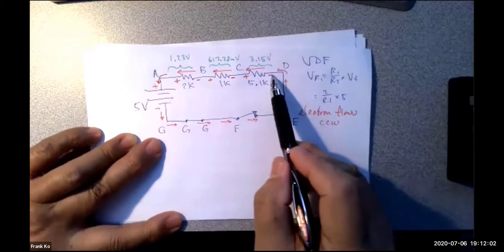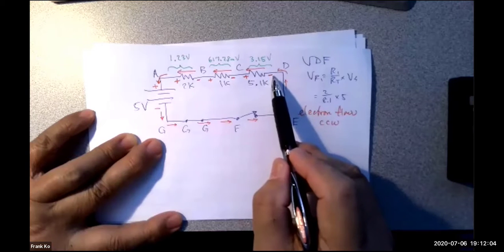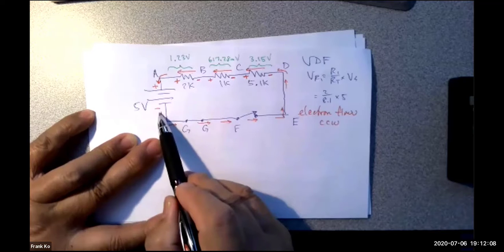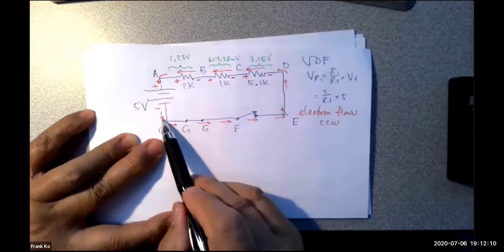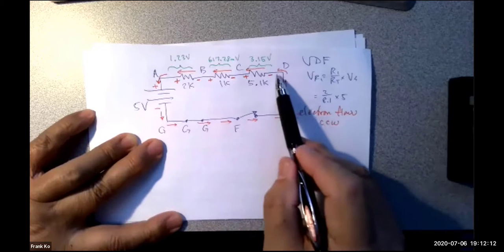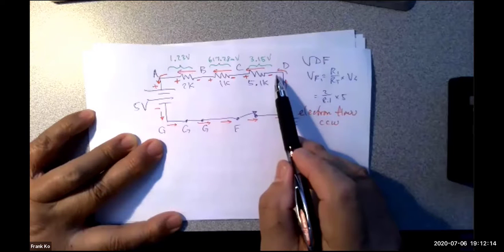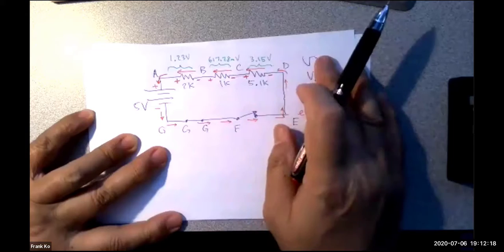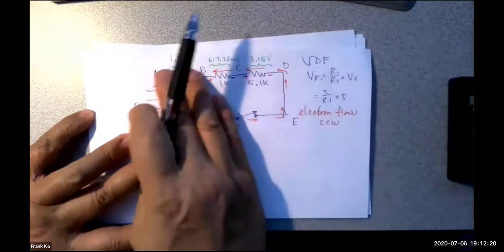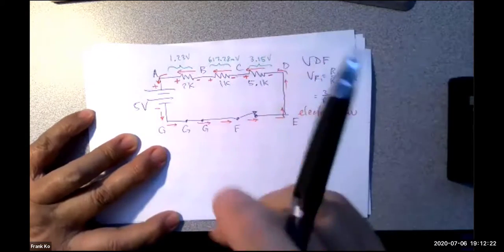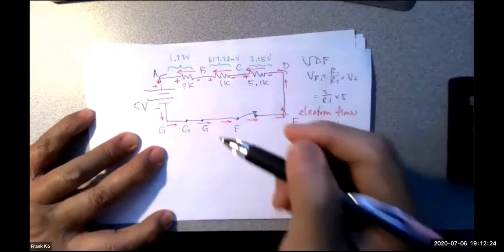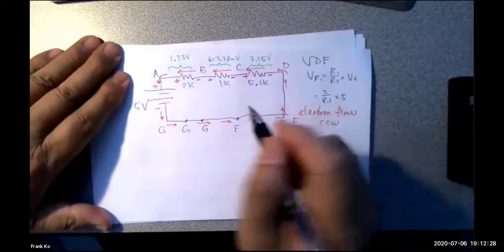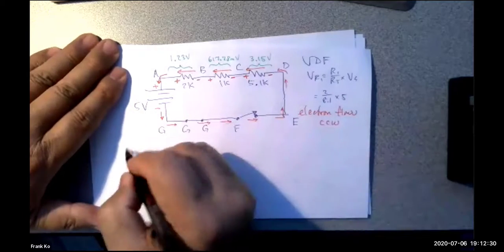This resistor over here, the last one, R3, has a wire that attaches all the way to the negative plate of the source. So as this plate is negative and there's a wire all the way to this side of the resistor, that side of the resistor must also be negative. So you've got to know the polarities across these, got to know the voltages across these. Now you can determine what voltages we're playing with, okay? So let's go ahead and take a point.